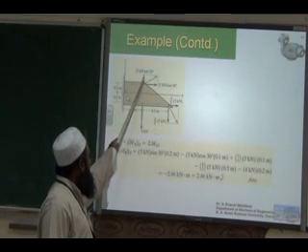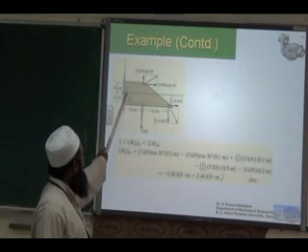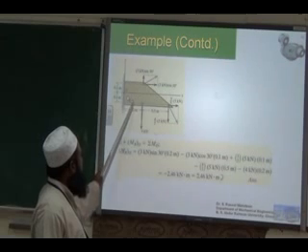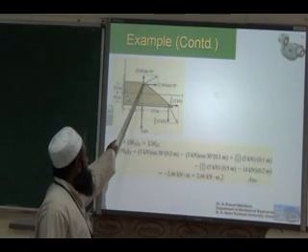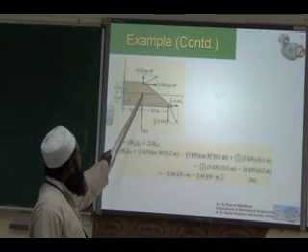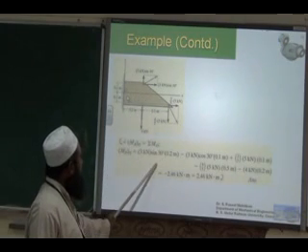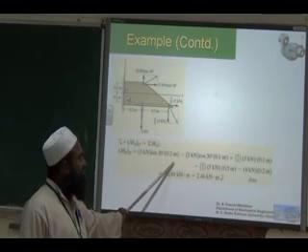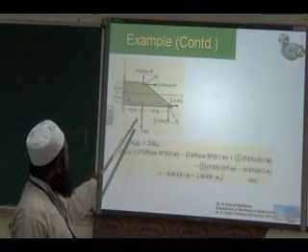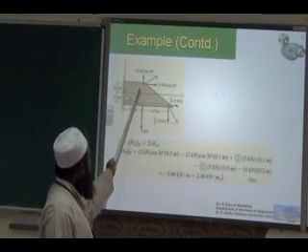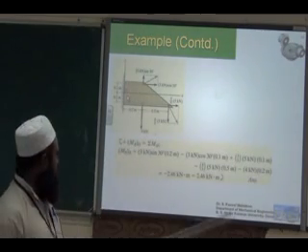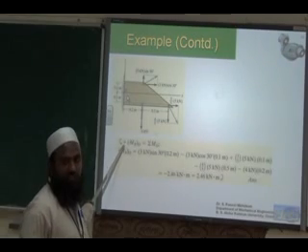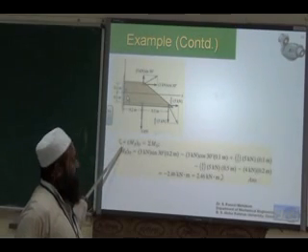So this is the vertical force. It takes moment about O. So the force times the perpendicular distance, 0.2. Say, for example, this force, 3 kilonewton sin 30 times 0.2. We consider the moment developed in the clockwise direction as negative and anti-clockwise as positive. That is why we put a conventional symbol here. Anti-clockwise is considered positive.